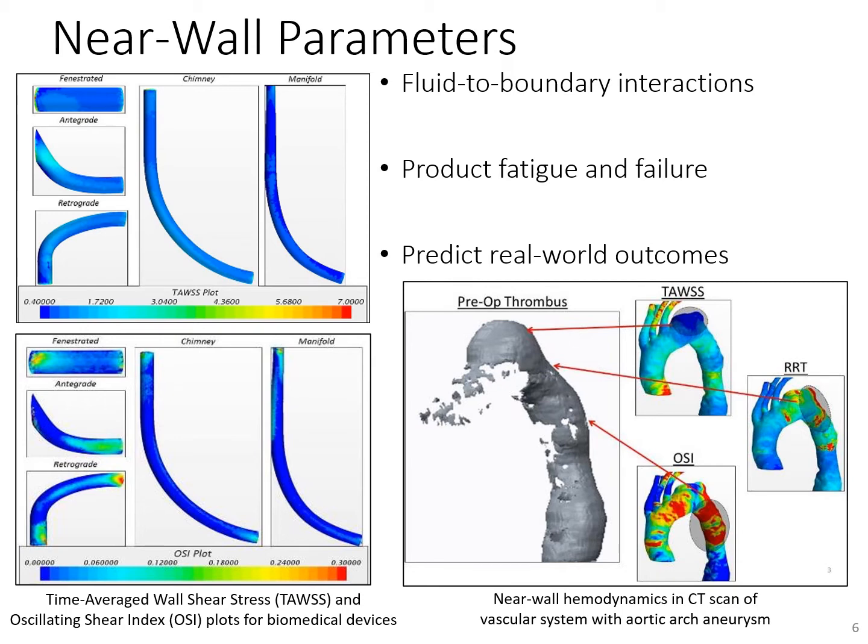In the examples provided here, the left images show the same biomedical devices for thoracoabdominal aneurysm repair as shown previously, but now analyzing the blood flow close to the device boundary and how it might affect the nearby arterial wall that it communicates with. Time average wall shear stress is essentially a representation of the degree of flow near the wall over a typical cardiac cycle, where high shear stress can cause premature device failure and fatigue, but low shear stress can cause platelet accumulation and clot formation.